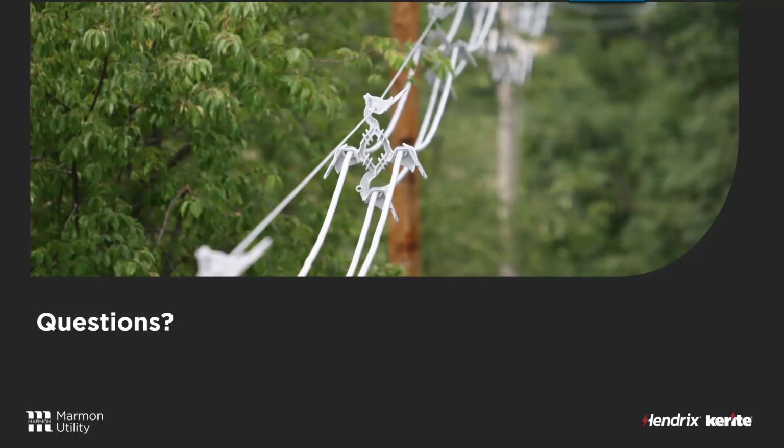So one attendee is asking if you can go into more detail on ice accumulation on covered cable. You mentioned that it picks up more snow and ice than bare, and he understands the diameter is larger, but it's been their experience that dielectric cables such as ADSS tend to pick up less ice, likely due to less thermal conductivity.